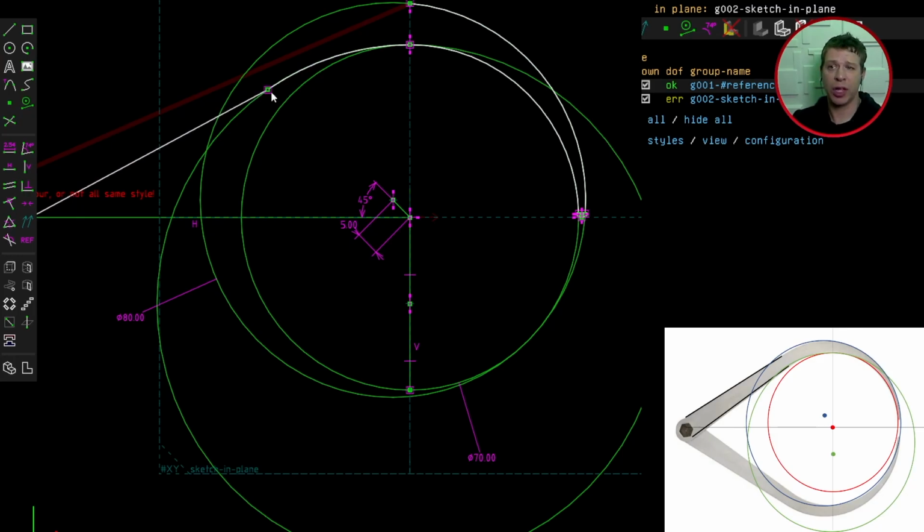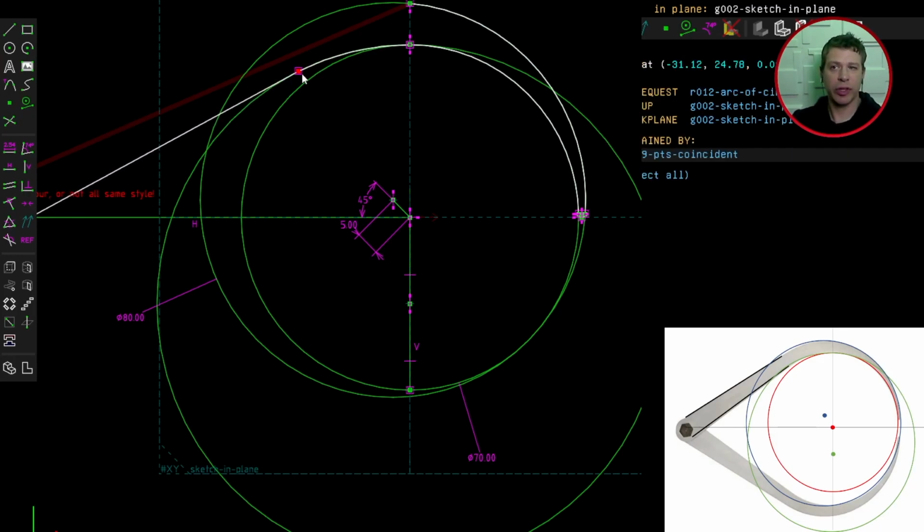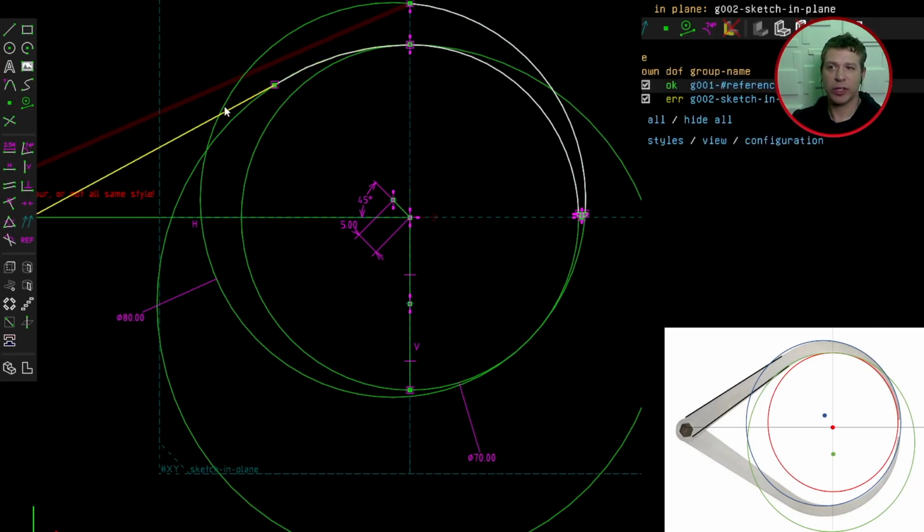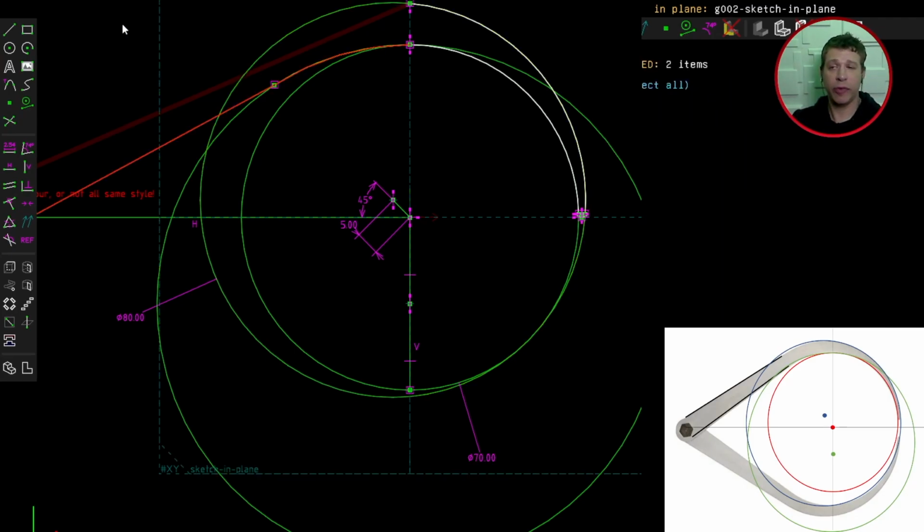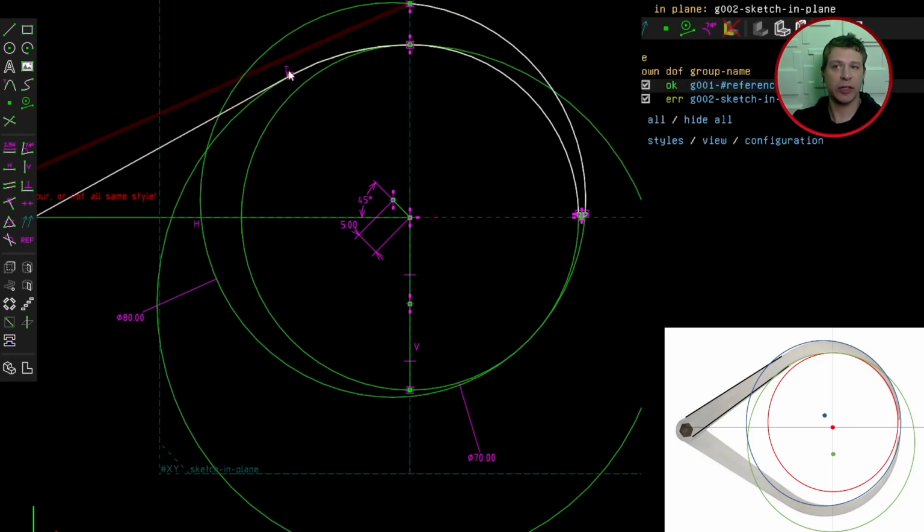Now the next thing I want to do is position this line correctly along the new arc that we've just drawn. I want this point to be along this curve where the line is tangent to the curve. So let's do that. So I'll select this line and the new curve that we just drew and click constrain to be tangent. And now you'll see a little T symbol here saying that this point now is correctly positioned where this line is tangent to that curve.